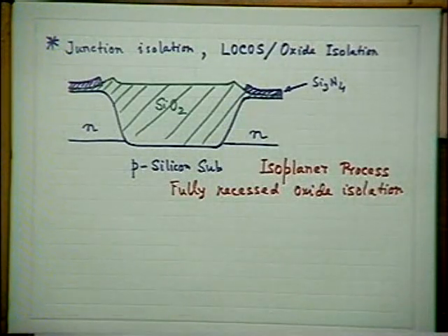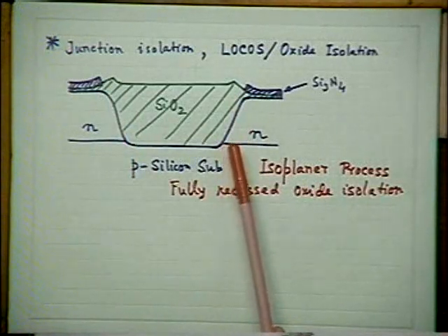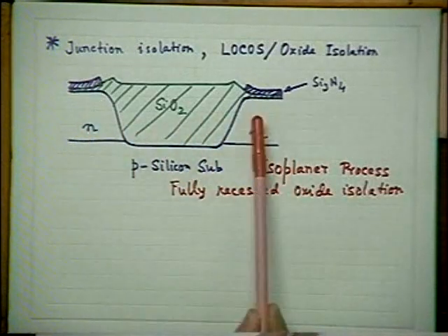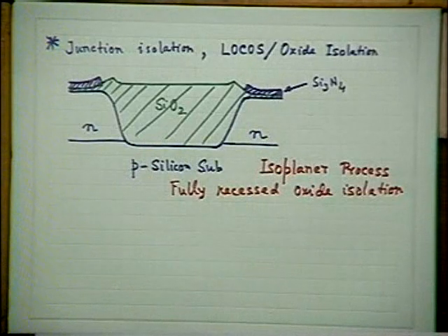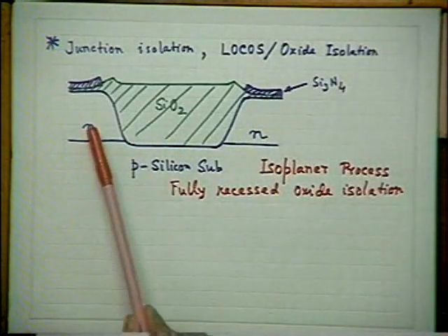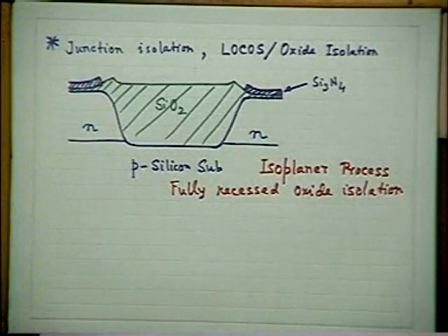But as you know, the demand of the silicon ICs has not been limited to only several tens of megahertz or even several hundreds. People are now developing ICs for very high gigabit capacity. And there even this kind of oxide isolation is not effective. There should be some other means. What is the drawback of oxide isolation? You see that, yes, the sidewall component of capacitance has been almost eliminated, but there is still some capacitive leakage, but that will be very small. But the bottom component of capacitance is still there, which is not very small. The capacitance of the PN junction in the bottom region, in the lower surface, still remains, and therefore for very high frequency operation, there is a limitation. I should also be able to reduce this capacitance, which occurs at the bottom.